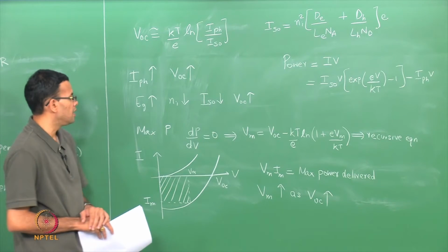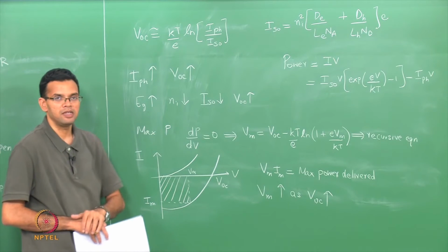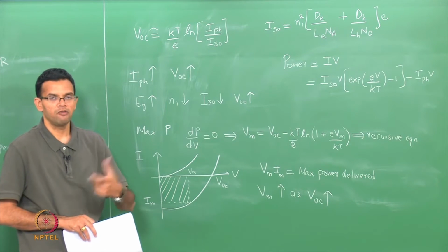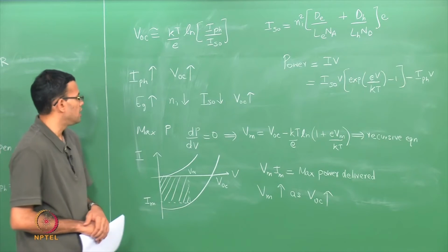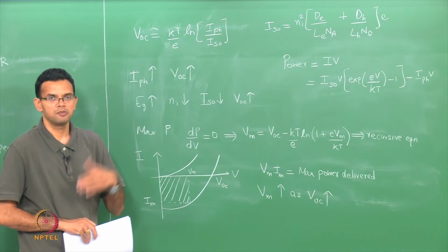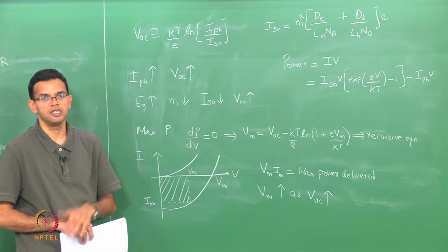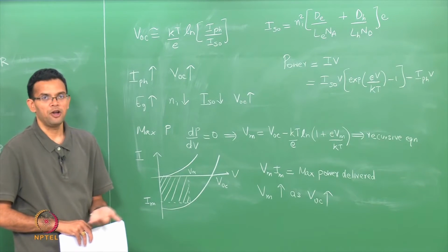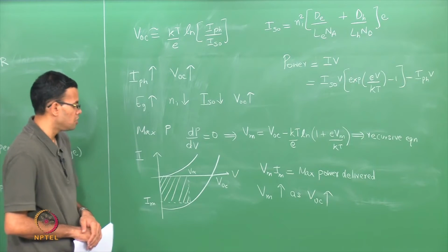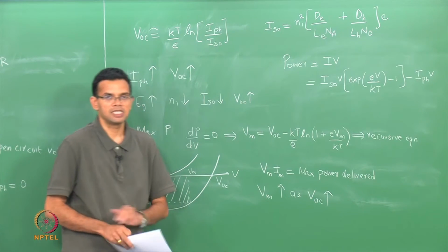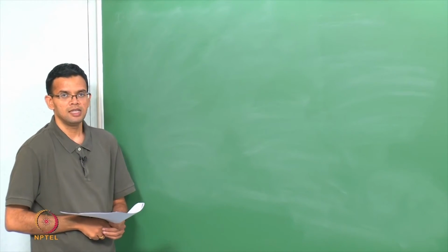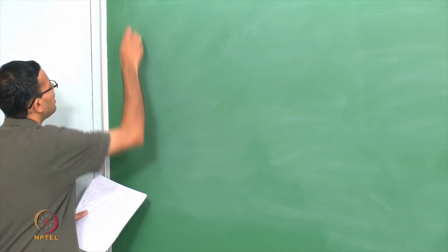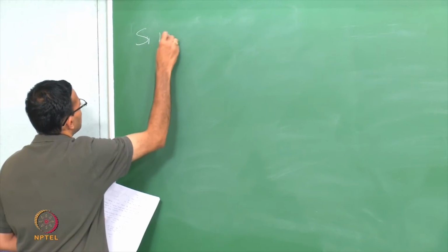The drawback in that case is that as your band gap increases, the region of the solar spectrum that is being absorbed will decrease, because as Eg increases, the corresponding wavelength for the transition will decrease. So, there is a trade off on what material you choose in order to get the maximum value of the power. So, conventional silicon based solar cells have efficiencies of around 22%.